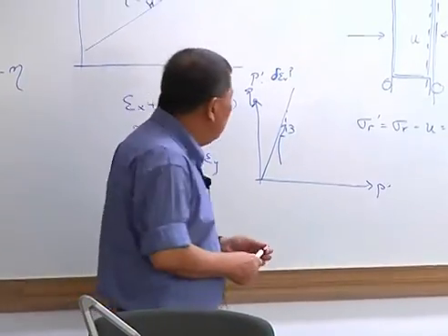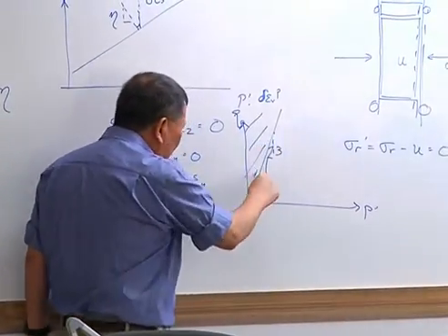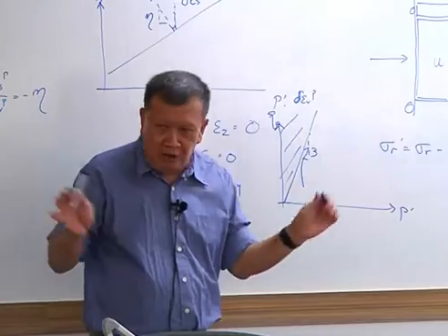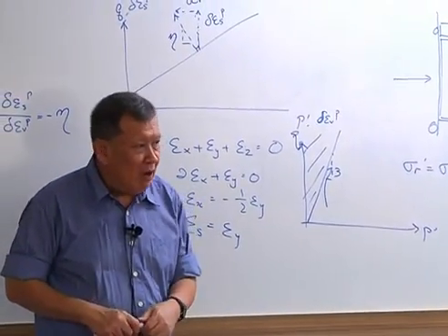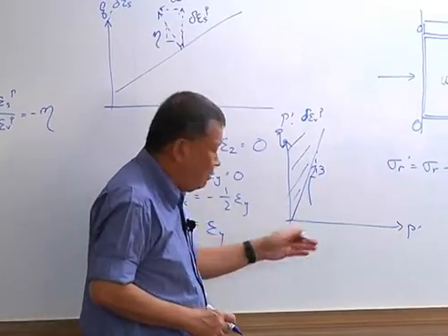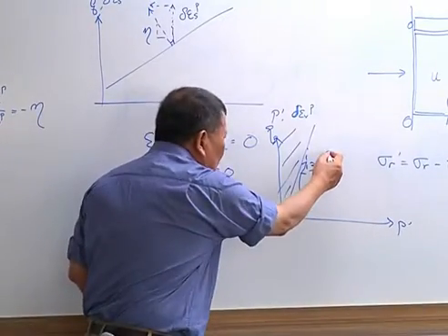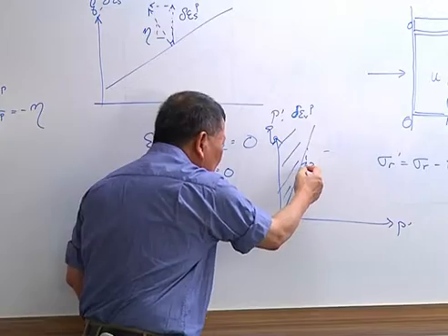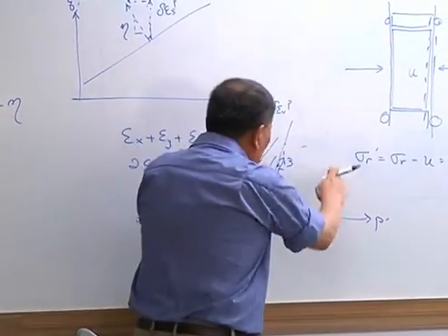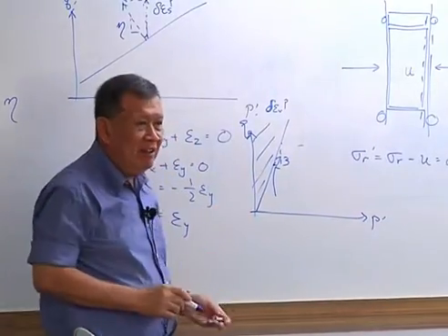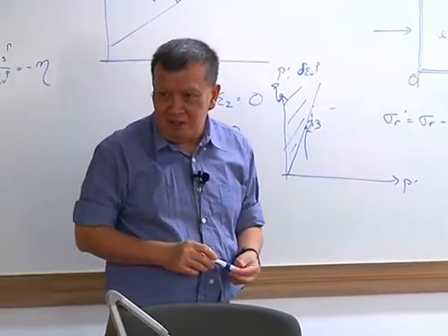Okay? So this region here, you cannot explore. It's out of bounds. If you use a triaxial test, you cannot explore that region. So yesterday somebody asked me, if I have a model, how do I get the c here on the p'-q space? No way, because your triaxial test result cannot come through to here. So you can only approach it by theory and say, I fit a curve to this portion, I project it back, this is where it hits. You get what I mean?